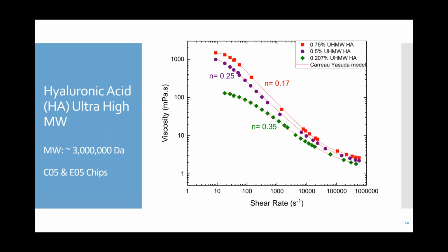With that in mind, now I'm going to go over the viscosity data that I collected with our m-VROC 2 and share some interesting results with you. This graph shows changes in the viscosity as a function of shear rate at a constant temperature of 25 degrees Celsius, collected for 3 different concentrations of hyaluronic acid with a molecular weight of about 3 million Dalton. I used a level generator protocol, something like the one I showed you in the previous slide. The results clearly show that these samples exhibit highly shear thinning behavior. For example, the viscosity of the most concentrated one, this one,